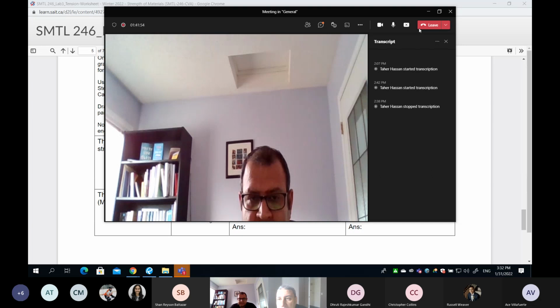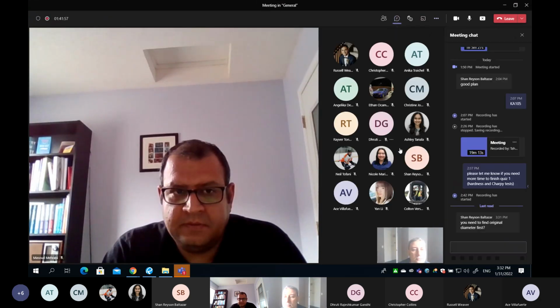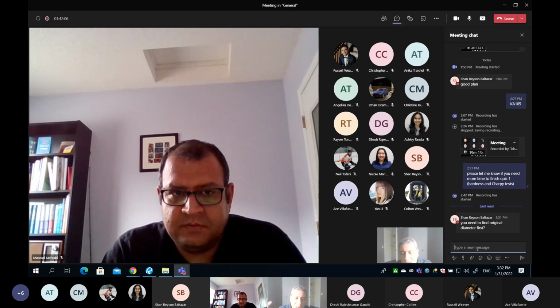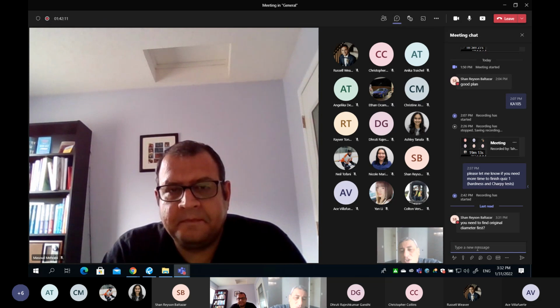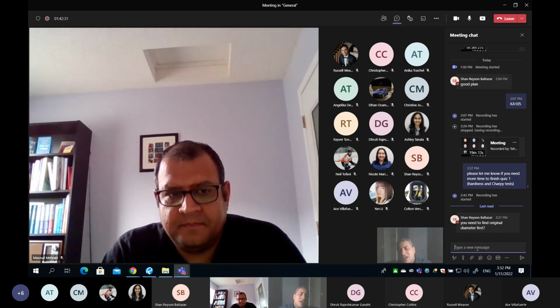Nothing's new. Any thoughts, any questions? The original diameter is given in the quiz. So we've done some measurement, and if the quiz gives you 3 numbers, you know what to do. It means you need to find the average of them, and based on the average, you find the cross-section area. Are you following? So if I give you 3 numbers for the diameter, all you have to do is find the average of D naught, then going forward, use the average of D naught in finding the cross-section area, and then the ultimate stress, and then the breaking stress.